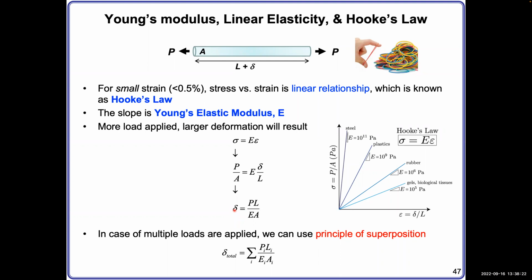In all finite element problems, we solve for the displacement first. As we showed in the previous calculation, we strike out the rows with no displacement, keep the unknown displacement on the left-hand side, and calculate that. From the displacement you can calculate many things. From force to displacement involves a few more steps.